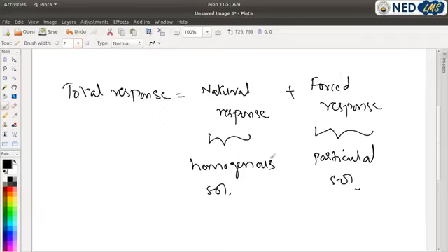In a system where a natural response grows without bound rather than diminishing to zero, the natural response is much greater than the forced response, and the system is no longer in control. This condition of instability might lead to self-destruction of the physical system if limit stops are not part of the design. For example, the elevator would crash into the floor if the design is unstable.